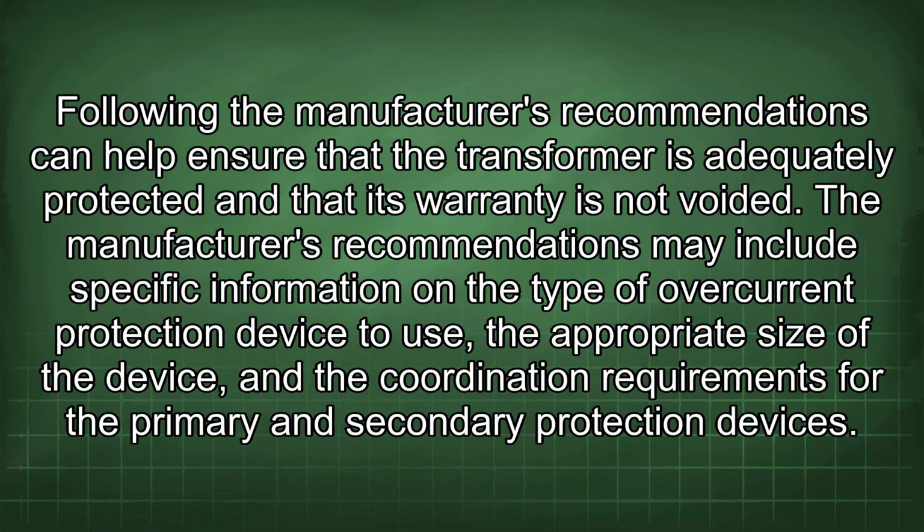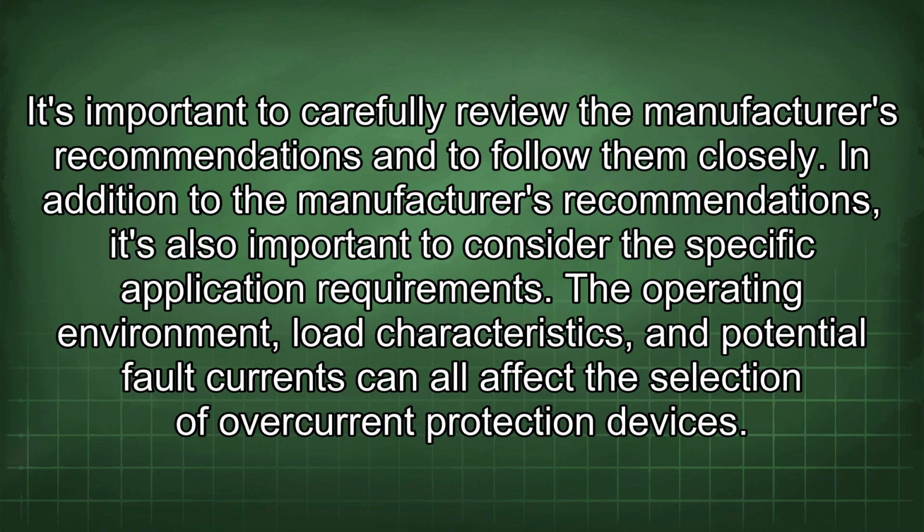The manufacturer's recommendations may include specific information on the type of overcurrent protection device to use, the appropriate size of the device, and the coordination requirements for the primary and secondary protection devices. It's important to carefully review the manufacturer's recommendations and to follow them closely.